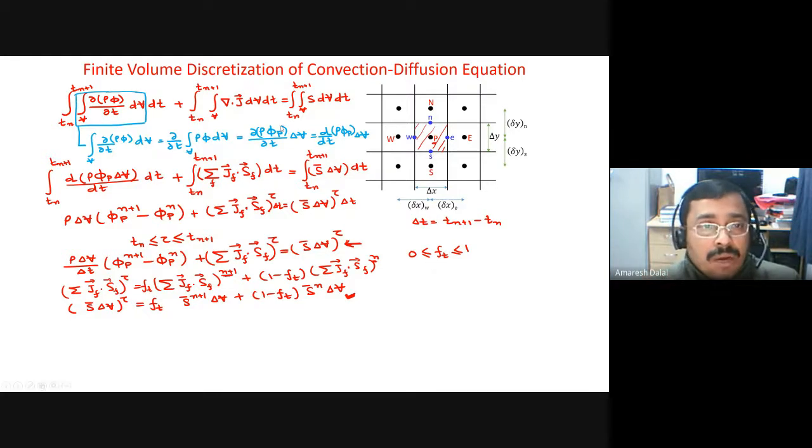Now first, if we use a non-deforming control volume, then we can take del of del t outside the integral, and we can write this first term as d of dt of rho phi p delta p. This term we already know how to discretize over the control volume.